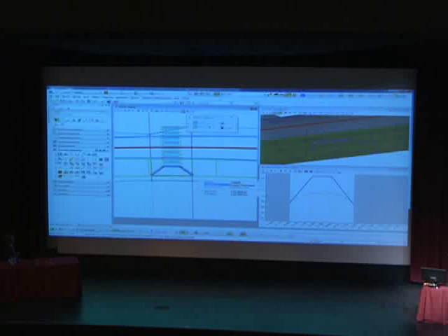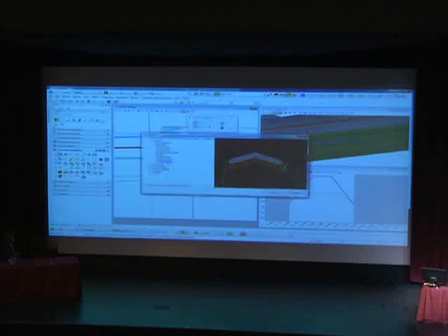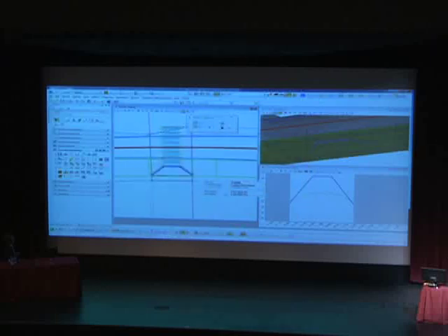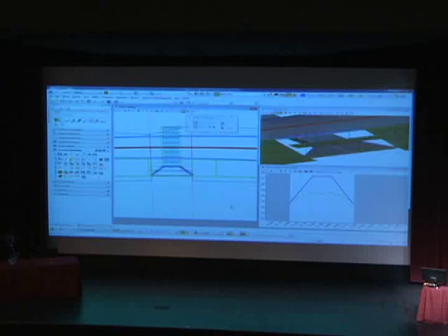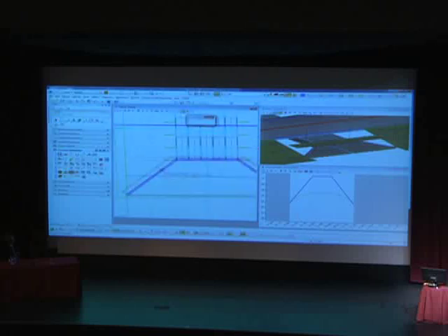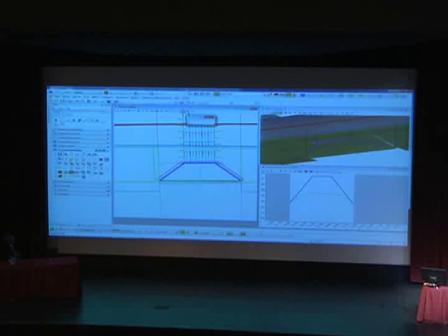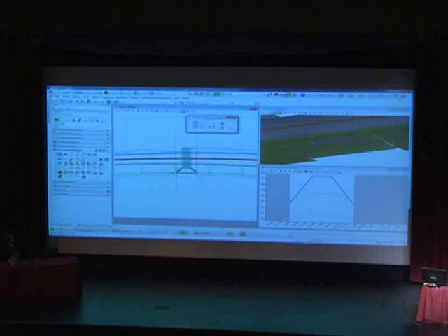So if I want this back of head wall to be right, I need to drop more templates along that area. So yeah, don't panic. It may look a little funky at first, but it's because I still need to add that as a corridor reference. So I'm going to go ahead and add that, and then the templates are spaced out. I need to click on my corridor, and right now it's at a 30% design model. I want to switch that to a 90% design model, and it's going to increase the amount of templates. So you'll see that shortly.